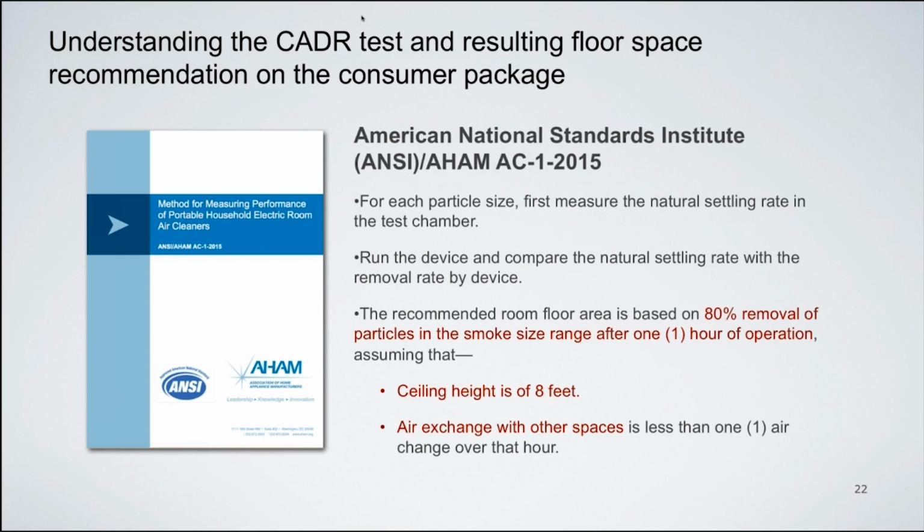So if you have, this is a test chamber test, of course, and they assume that it's 8 feet because that's what they're measuring, or they're measuring something else. In any case, they're normalizing it to an 8-foot ceiling height, a certain cubic volume of the space. If you had a room in an older building, let's say a 19th century building with really tall ceilings, or a very modern building, maybe an apartment building with 10-foot ceilings, as you might have in the center city of San Francisco or Denver or Boston or Miami. Typically, those ceilings are 10 feet tall. So then you're not going to get 80% removal from that because you have more cubic area.